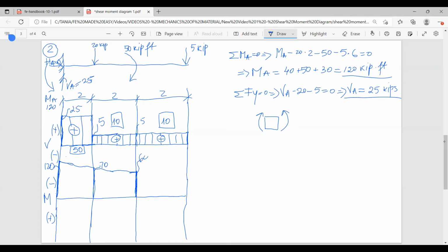So here from 60, and this is very important because it's very easy to make a mistake. So from 60, look at the beam. We have 50 kips, and we're coming from the left side. The moment goes clockwise, which means we're going to go towards positive. So 60 going towards the positive with 50, I'm going to end up at a value of 10 here.